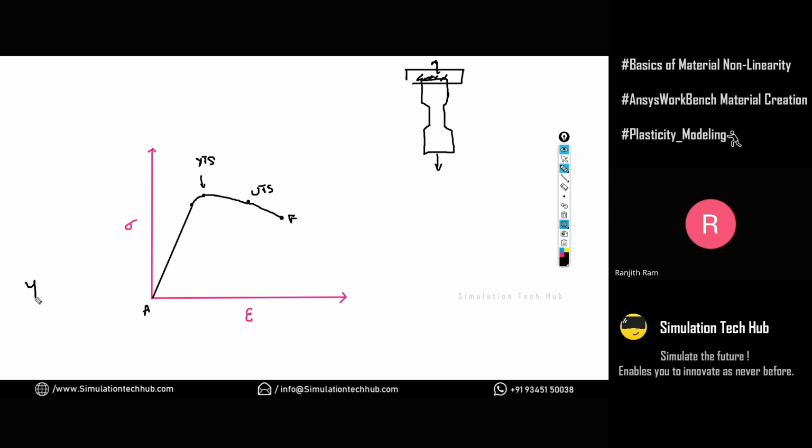As we discussed earlier, the term Young's modulus is the slope of this line. It's nothing but the slope of this line. We know this is the Hooke's law region, because stress and strain are proportional to each other within the elastic limit. Up to the proportional point only, stress and strain are proportional. After that, it won't be proportional. Also, all of this is within the elastic limit, which means if we remove the load, it will come back to its original state.